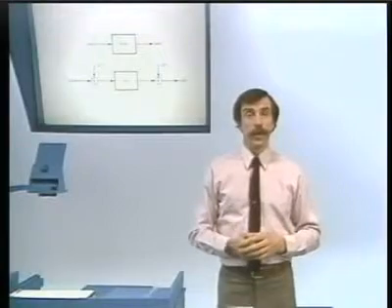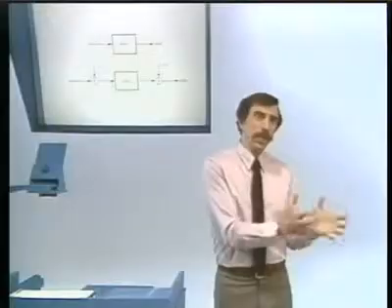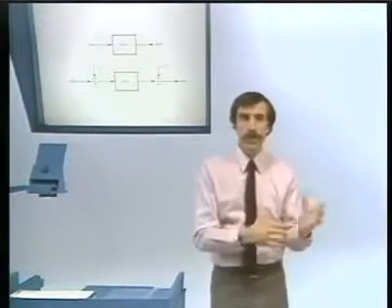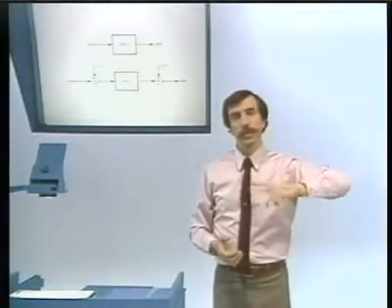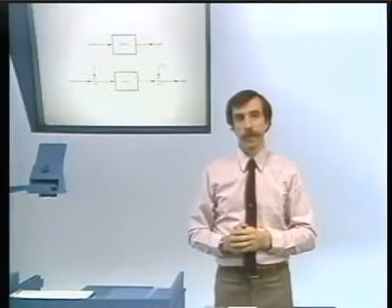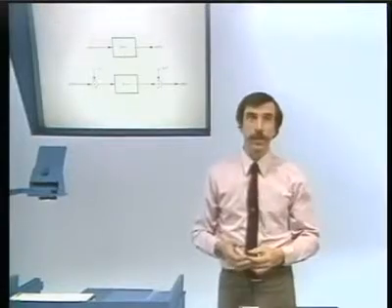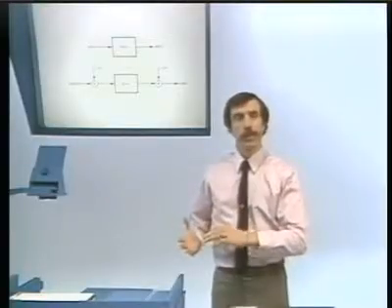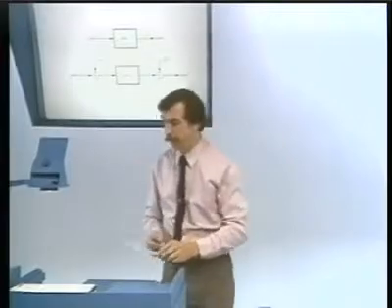Well, one way to do it, instead of shifting its frequency response, is to take the original signal, shift its low frequencies to high frequencies and its high frequencies to low frequencies by multiplying the input signal by -1 to the n, process that with the low-pass filter, where now what's sitting at the low frequencies were the high frequencies, and then unscramble it all at the output so that we put the frequencies back where they belong. And I summarize that here.